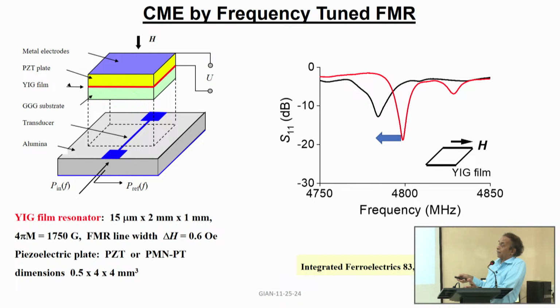There is a ground plane made of alumina. Then there is a single strip of metal. Then when you pass microwave through this strip, there is current. And we know that if there is a current, there is always a magnetic field, correct? So it will produce a microwave magnetic field.